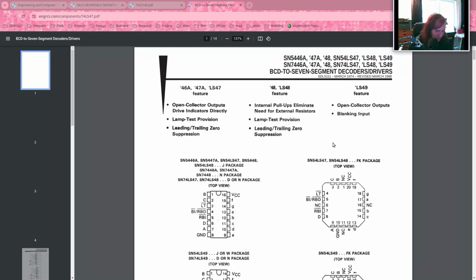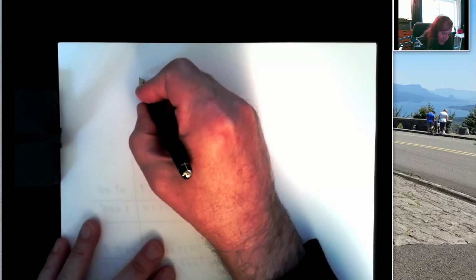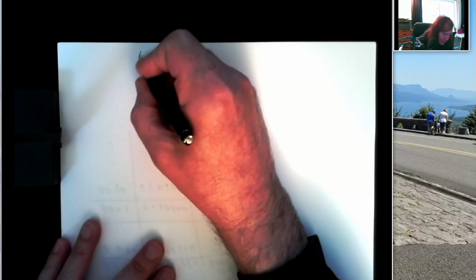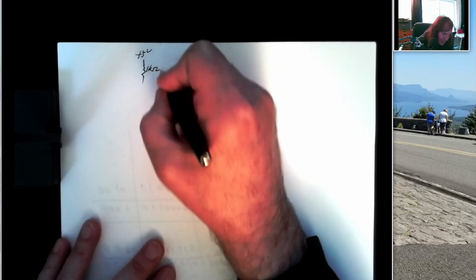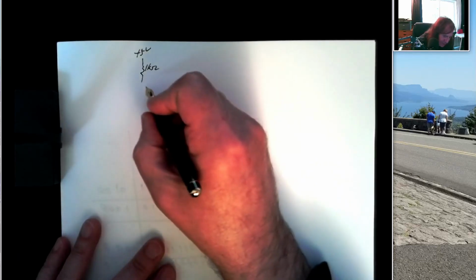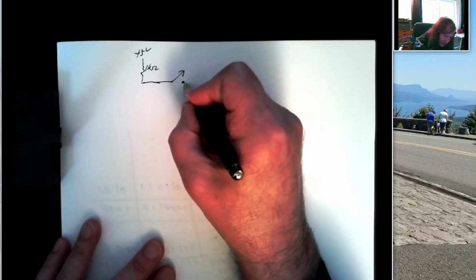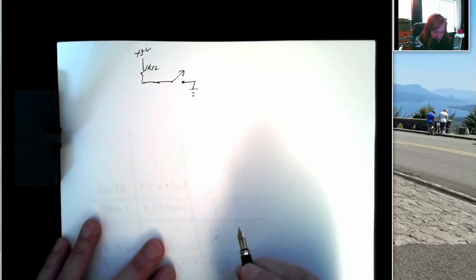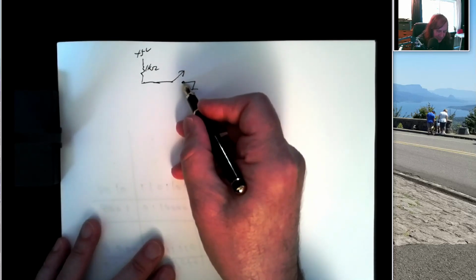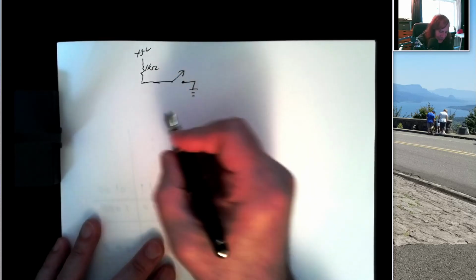So one more thing I want to just touch on in here, and we'll get into this more as we dig into some of the labs. But you know, when we design schematics for circuits, we do things in a very standard way. If we have an input, we might pull that input up through a 1K ohm resistor, and we make a squiggly line for the resistor, and we draw a switch like this, a little arrow going up. And we show the switch open, but we put a little dot here to say if you close the switch, this gets connected to this.